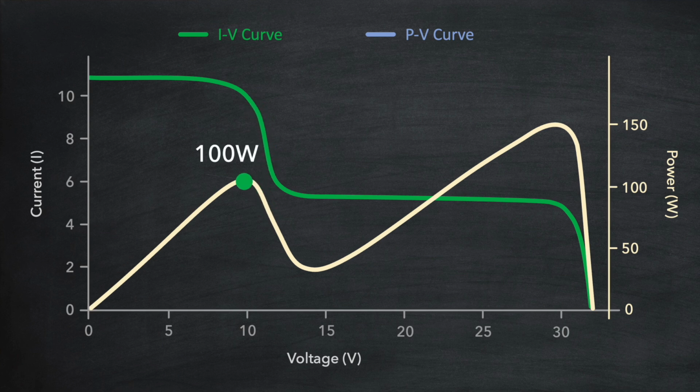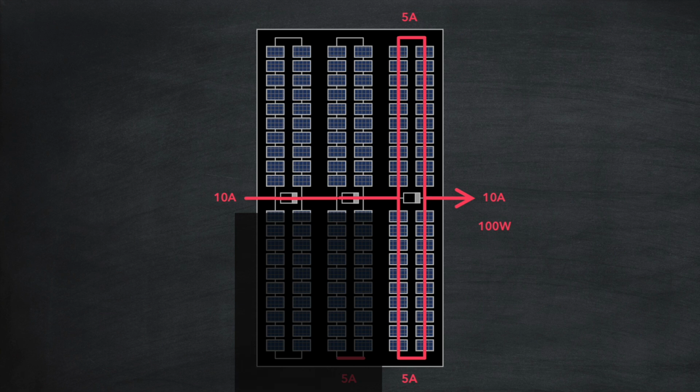On older inverters, this was achieved using a very basic algorithm, identifying and selecting the first peak it came across. But newer inverters are able to perform what is called a global sweep, identifying all the local peaks and then selecting the highest one. If we go back to our panel then and limit the current entering it to 5 amps, you can see that something different happens.